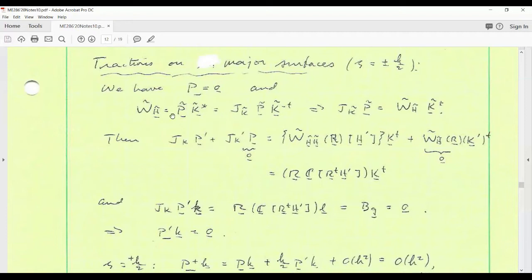And we get the prime of dW/dH times K transpose, which gives you this by the chain rule, evaluated at H on the midplane where H is equal to R, K transpose, and then take the derivative of K transpose with respect to zeta, which is the same as the transpose of the zeta derivative. But in any case, dW/dH on the midplane is 0, just from this equation. So we get this. We already know what this is from a previous discussion.